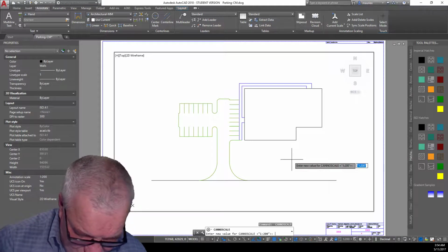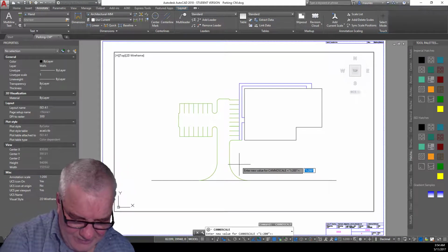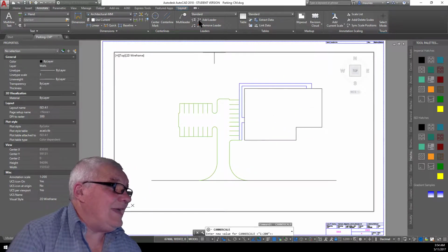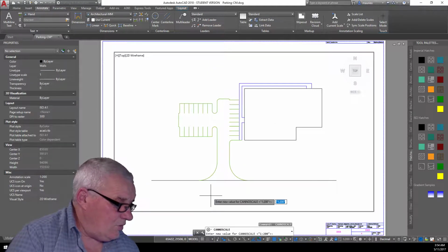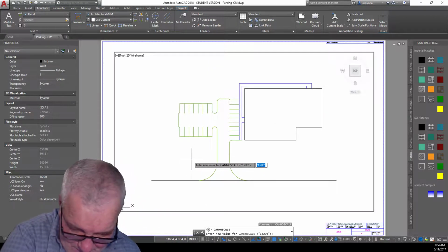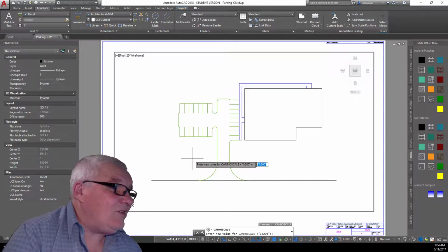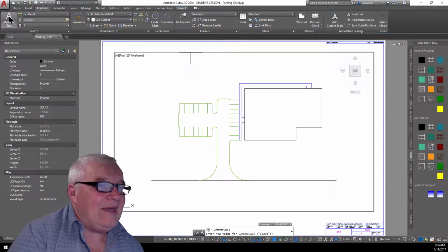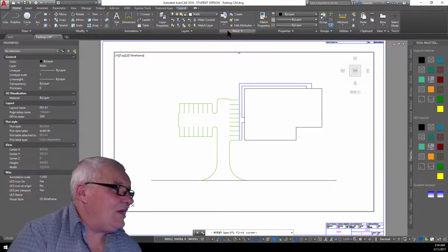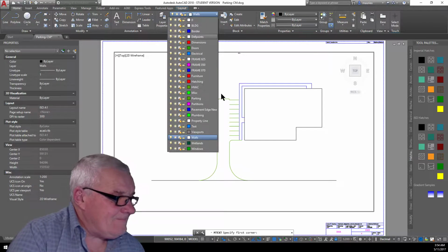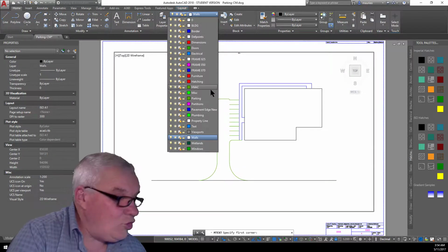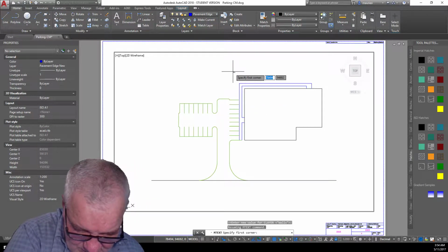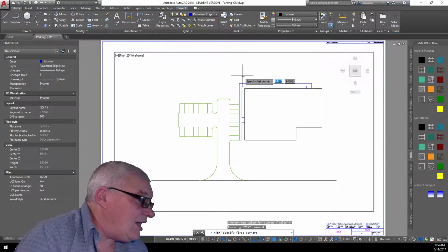Okay, now activate the viewport and make the pavement edge layer current. So yep, activate the viewport, which is the big one around there, and make the layer pavement edge new. Pavement edge new. Okay, and hatch the sidewalk with HR concrete.